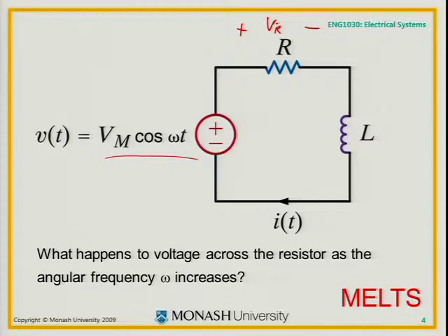as I increase omega. You can think about how an inductor behaves at low frequencies, or even DC. That's the limit of low frequency. How does an inductor behave at low frequencies? How do you think it behaves at high frequencies? What you know about it is that V equals L times the rate of change of current. We said we know then what it looks like at direct current or really low frequency. What happens as the frequency increases to an inductor? Does it become sort of like a bigger resistance or a smaller resistance?